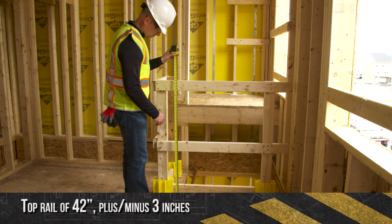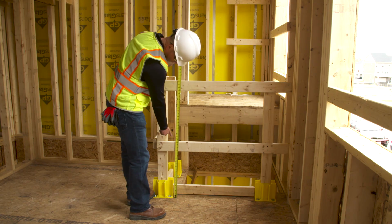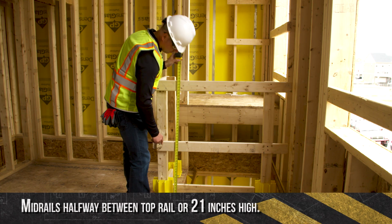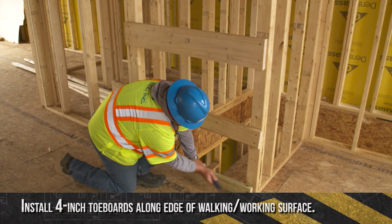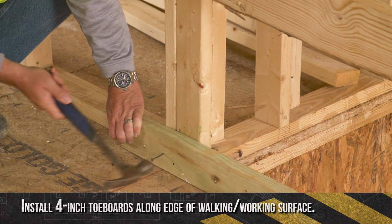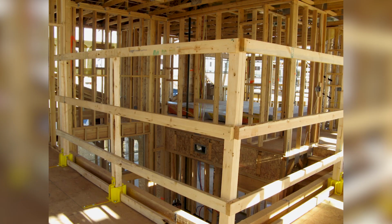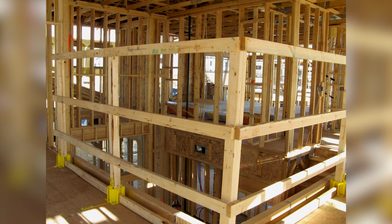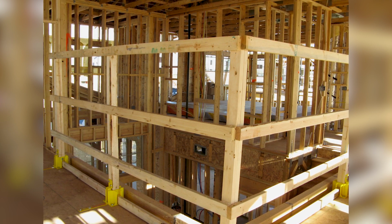Install top rails at 42 inches high, with mid-rails placed halfway between the top of the guardrail top rail and the floor or walking working surface. Also, install toe boards at a minimum of 4 inches along the edge of the walking or working surface to protect from falling debris and objects such as tools or materials. In certain instances, such as when workers are using stilts or ladders, the top rail would need to be raised the equivalent height to protect the worker from the fall hazard.